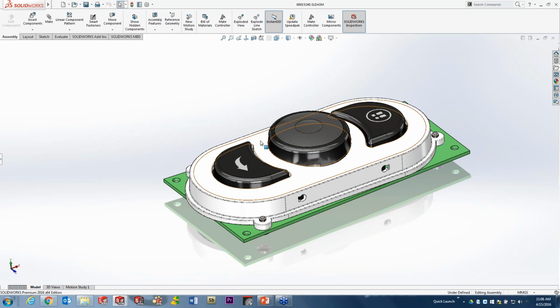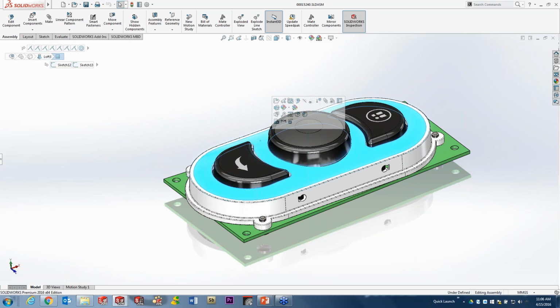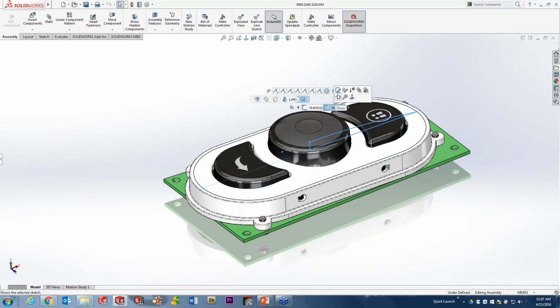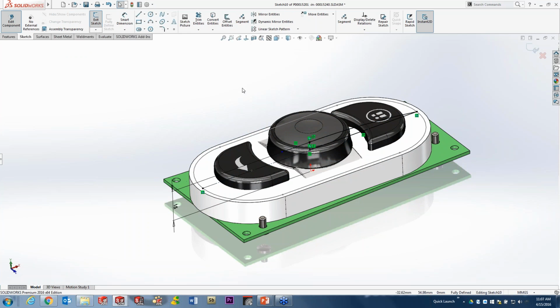Now when I go ahead and select this, I'm not a big fan of the inconvenience of having to go to the upper left-hand corner to grab this. So they've also built in the D key. Now this is just a hotkey like anything else, but if I tap the D key, which is pre-programmed, it'll actually bring those breadcrumbs to your cursor position. Now with that, I can go ahead and action on anything I'd like, even scroll through the sketches if there's more than one, and to select it, simply go ahead and edit that.